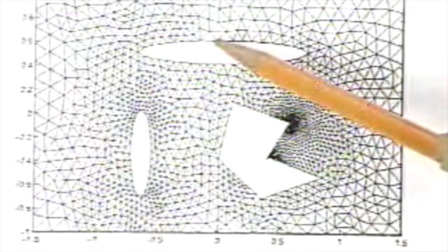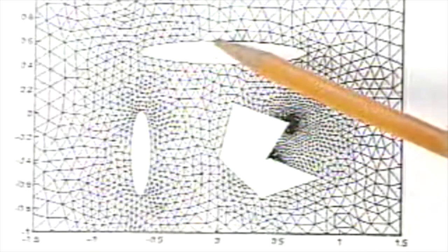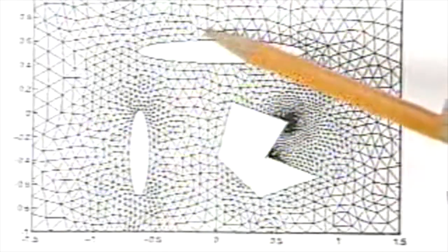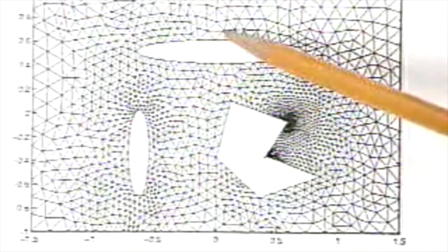That means the velocity on the wing was 0. It gives you a specific value to put right there. But that boundary condition then propagates out into the rest of the domain, because this 0 affects these 2 points, which then affects that one, which then affects everybody else. So your boundary conditions couple back in to some big matrix, this Ax equal b that we're going to construct.